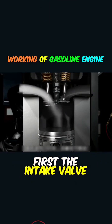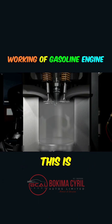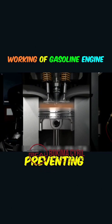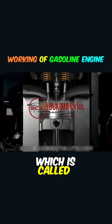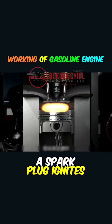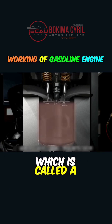First, the intake valve opens, the piston moves downward, and the mixture of air and gasoline flows into the cylinder. This is the intake process. The intake valve then closes, preventing further inhalation of fuel and causing the mixture to be compressed at high temperatures, which is called compression. An explosion occurs when a spark plug ignites the compressed mixture of gases, and the force from the explosion drives the piston downward, which is called a power stroke.